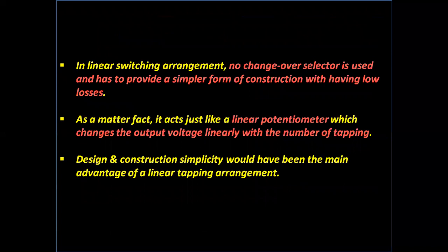In the linear switching arrangement, no changeover selector is used, which provides a simpler form of construction with low losses. As a matter of fact, it acts like a linear potentiometer, which changes the output voltage linearly with the number of tappings. Design and construction simplicity is the main advantage of a linear tapping arrangement.